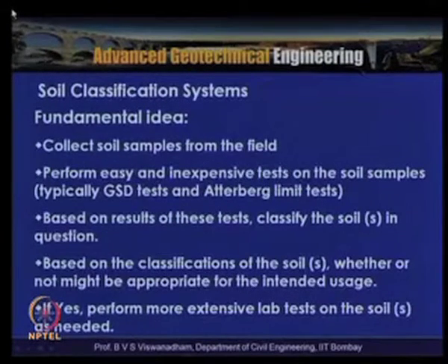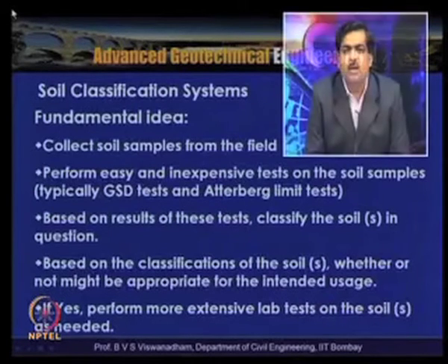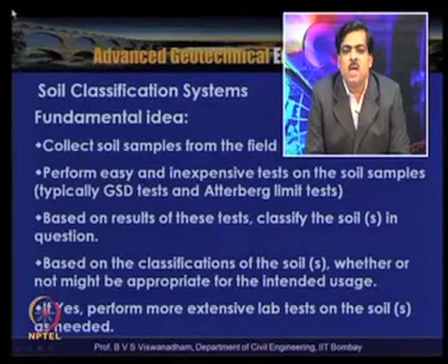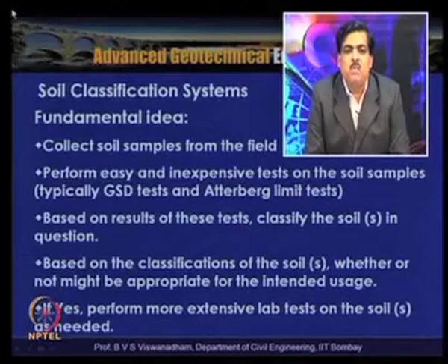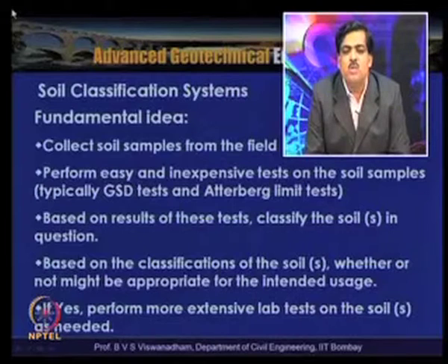That means that whatever soils are tested, they can be placed in a class, which helps classify the soil in question. And based on the classification of the soil, whether or not it is appropriate for the intended usage can be guessed. If yes, perform more extensive lab tests on the soils as needed. So if the soil classified in a particular group is suited for a particular application, then perform more extensive lab tests on the soils as needed.